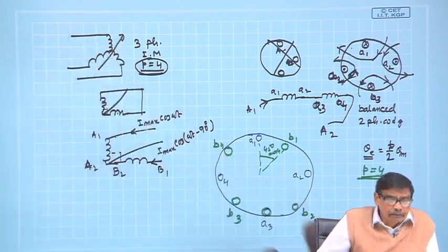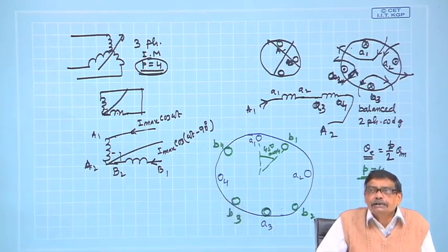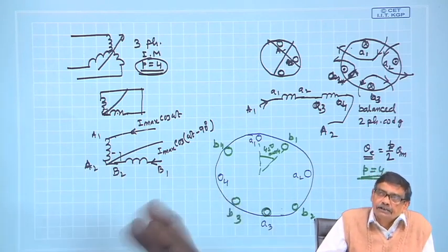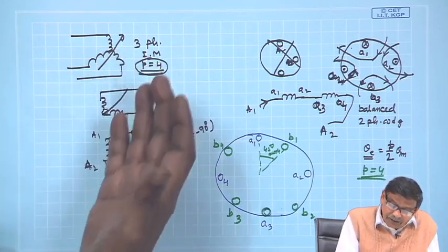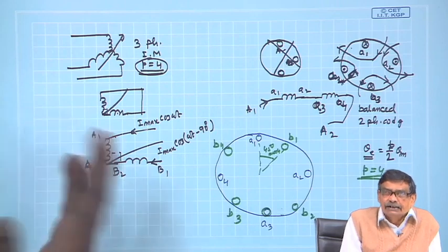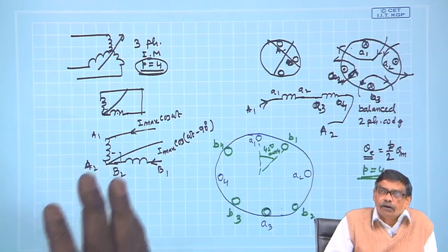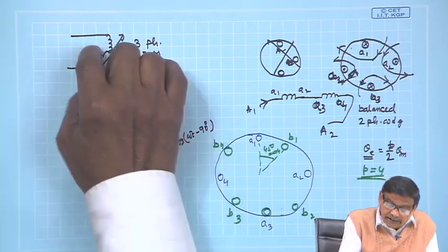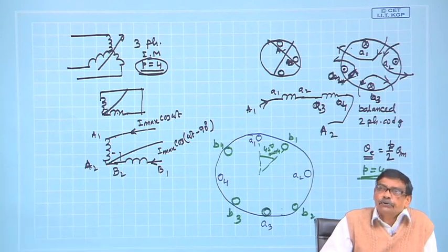Then stator will fail to understand whether on the rotor there is a two phase winding or three phase winding or a six phase winding. It cannot distinguish. It only sees how it reacts to the rotor, because rotor creates a rotating magnetic field of same number of poles as that created by the stator currents. That is all that is needed to produce steady electromagnetic torque.